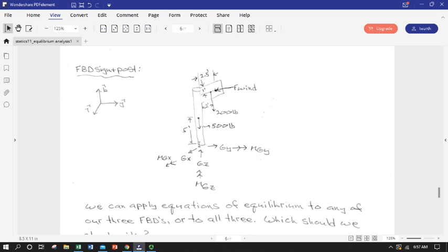So if we were looking for the ground forces, which is what we were asked for, this single FBD should give it to us. We won't know anything about what's happening between the sign and the post. So, if we had to select a fastener or look at maybe the strength of the material in the pole in the radial direction, not wanting the pole to split as this and have the sag, we'd have to go back up to our other 2 FBDs. But if all we need to know is how to design the foundation, this one will give it to us. We know that right off because we have 6 equations and 6 unknowns.